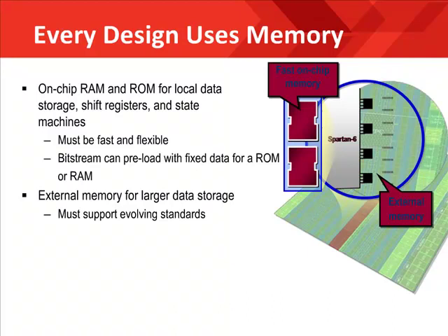Spartan-6 also includes dedicated and programmable memory controller blocks which allow you to integrate external memory controllers inside of your FPGA. The MCB, or memory controller block, allows you to easily support large data storage applications in which a large off-chip memory component is needed. Just like our soft memory controllers, the MCB is designed to be programmable, so it can support a number of different memory controller standards. This allows the FPGA to be flexible and quickly evolve to meet customer needs of a particular application.